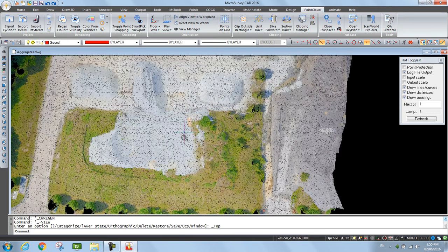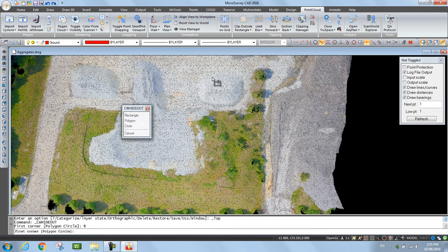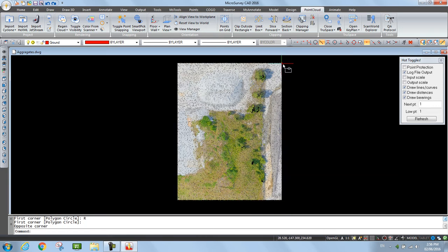we've got a combination of bare ground, but we've also got some trees here, and the trees, if they were part of that surface, would generate an inaccurate model of what the real ground looks like. So we'll use some tools that allow us to filter through those trees. Just so that I can focus in this area, I'm going to set up a rectangular clip. And there we're focused right in.